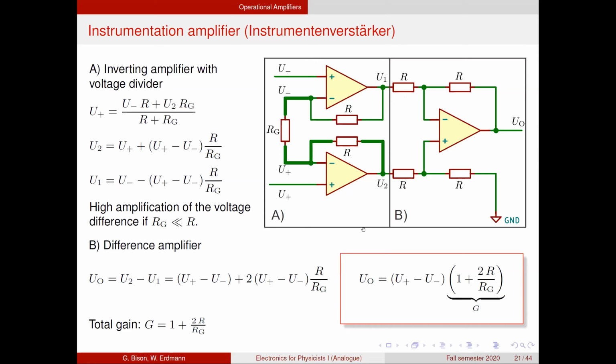So the first step, and actually this is also part of your project, is a combination of two op amps that are kind of crosswise connected to each other. And in order to understand what this system is doing, it's really important to use the rule that the potential at the two input terminals is the same.